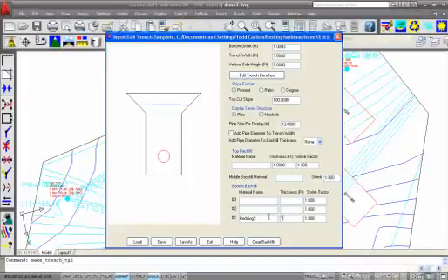Say bedding 1 at a foot, and bedding 2, and I'm going to put this at 0.01, and I'll show why in a minute. And then a top, let's call it stone, of half a foot. Okay? So we have a bottom bedding, middle bedding defined, which is 0.01, and then stone at half a foot.